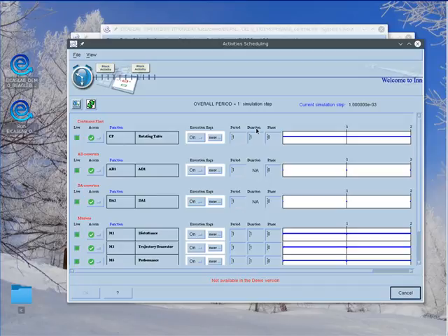The duration is emulated considering, for any block, 2 periodic functions. An execution function dedicated to update the block state, and an output function dedicated to provide the output of the block only after the stated fixed duration. This approach allows to perform the like real-time simulation, avoiding wrong time zero simulations.